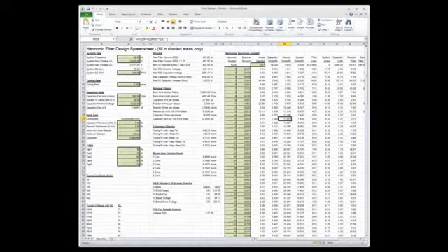The only switches that I'm aware of in capacitor filter banks are switches used for grounding. In other words, you're in an energized condition, then it goes to a middle condition where it's not connected to anything, and then you ground it for safety reasons. You have to have a real upstream breaker to open and close your filter.